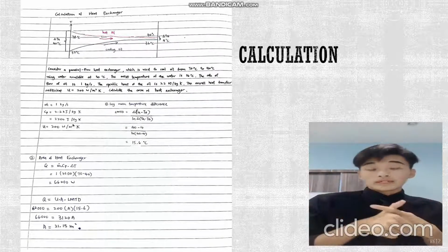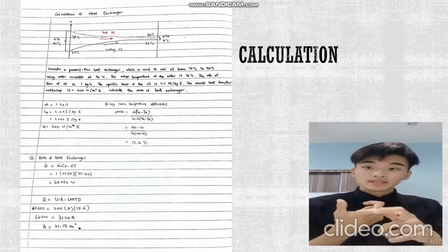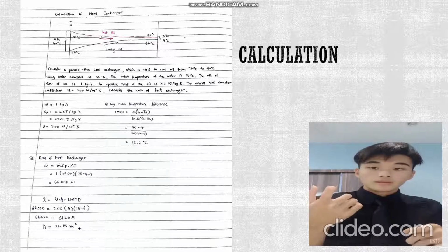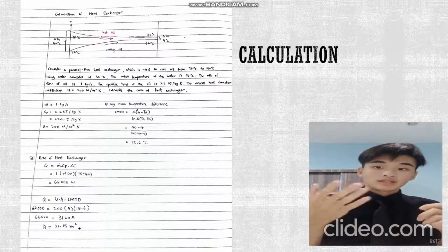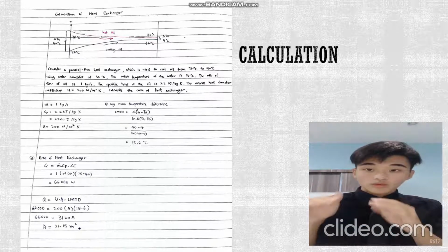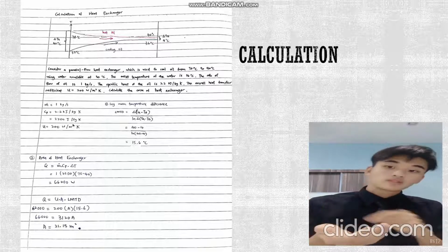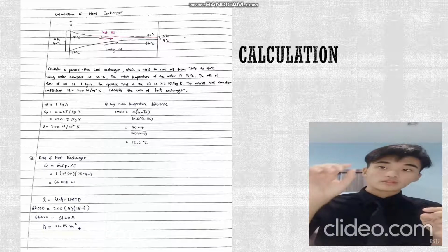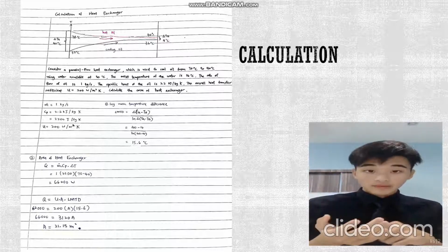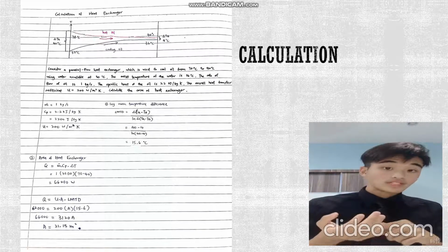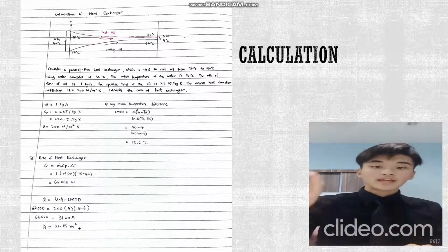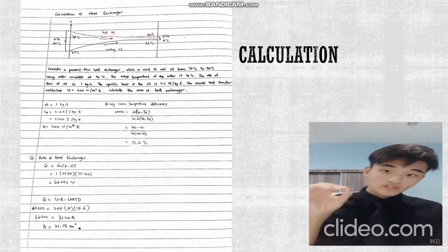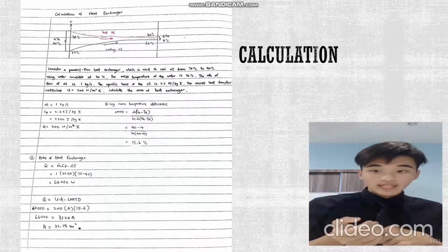The mass flow rate and the specific heat we get from the information, then we substitute into the formula, that is 1 times 2200 times the delta temperature, we use the hot oil, 70 degrees Celsius minus 40 degrees Celsius, and we get the final answer of 66,000 watt for the heat.